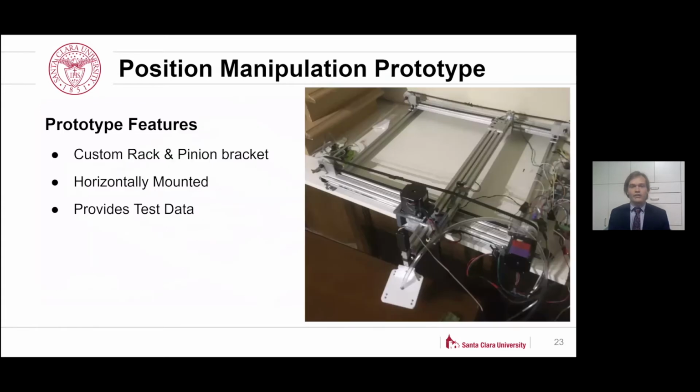So this is the physical build of the structure, which was completed during spring quarter. This design was used to provide us with our performance data, given speed, repeatability, and gripper data. One other thing to note is there's the 3D printed mount for the Y stage rack and pinion, and everything on the Y stage is horizontally mounted in order to provide less vibration from the steppers and to keep us more stable.